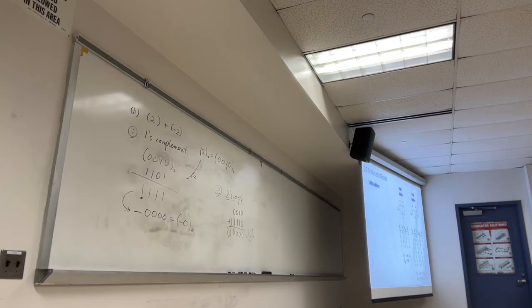And the major difference between the half adder and full adder. Anybody knows what's the difference between the half adder and full adder? Look the same, right? So half adder, there are only 2 inputs. Full adders, 3 inputs. In the diagram, there is no carry in. Full adder, we have to have a carry in. Any adder we have is using the full adders.